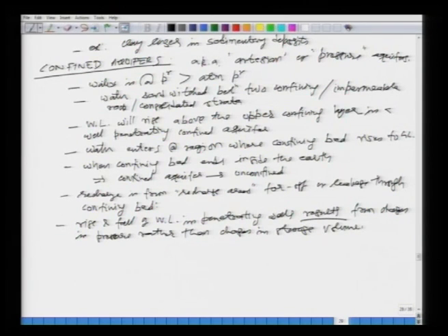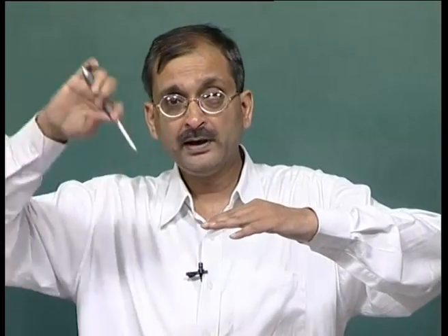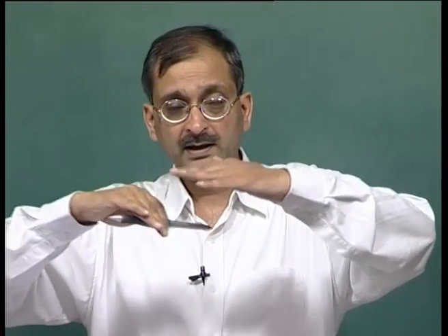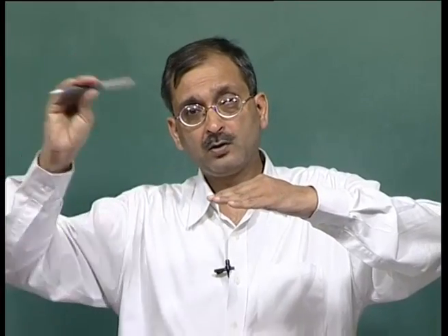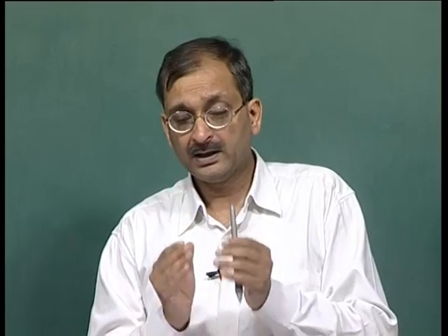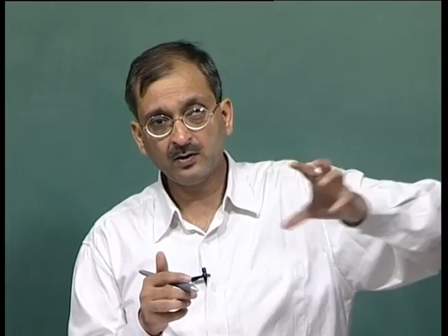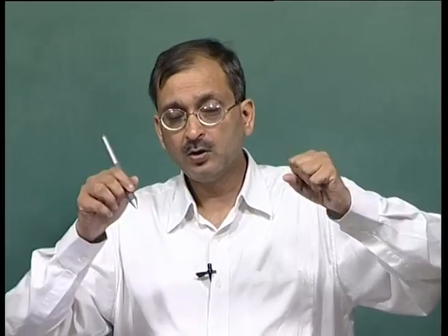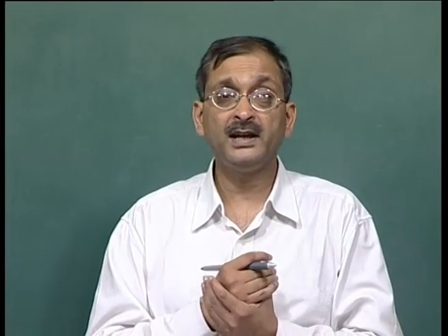Okay. So, you have a confined aquifer. If you tap into it, if you have a well inside a confined aquifer, you are drawing the water out. Where is this water coming from? It is actually not the storage. You have a recharge, which is a continuous conduit. So, changes in pressure will take place. There will be very little change in the storage volume in a confined aquifer.